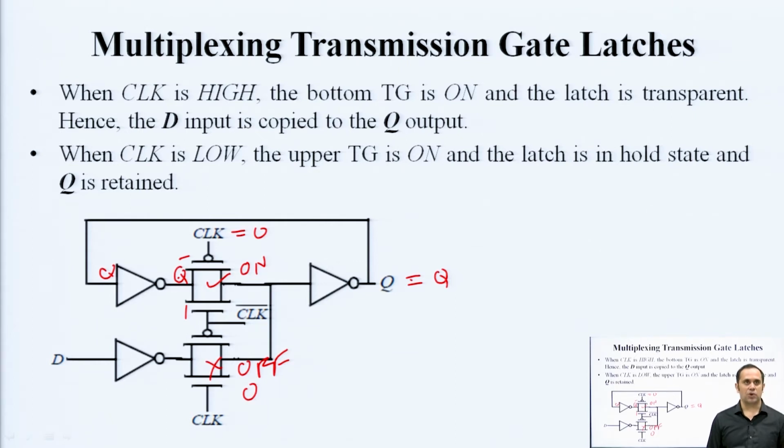Depending upon the inputs to the clock, you can replace the clock with an enable signal also here, you can make it active high, you can make it active low. In that case, you can implement this latching circuit and again this is still a level triggered circuit.